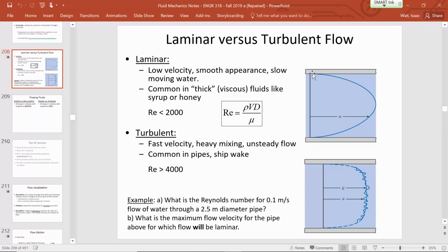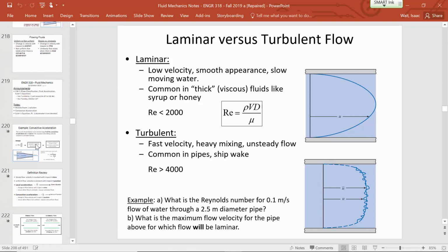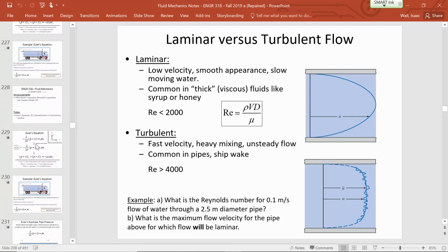So remember, in laminar flow conditions there isn't enough velocity and not enough energy for these layers to interact with each other. And he mentioned the phrase the no slip condition, so that at the edge of the pipe the velocity is 0, and even in a pipe where we have relatively fast moving liquid, there's going to be some thin layer inside of the pipe where you have a laminar section where the velocity is low enough. Even if in the entirety of the pipe cross section you don't have laminar everywhere, near the edges of the pipe it will be laminar. So I just thought that was kind of an interesting illustration of the special case of laminar flow.